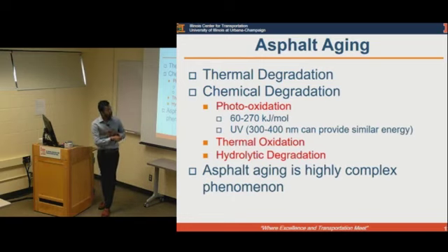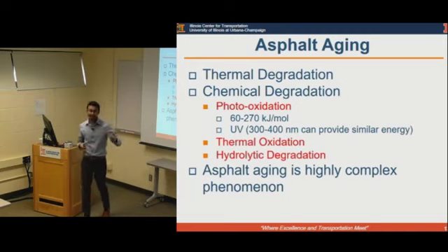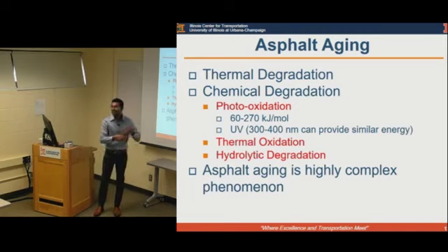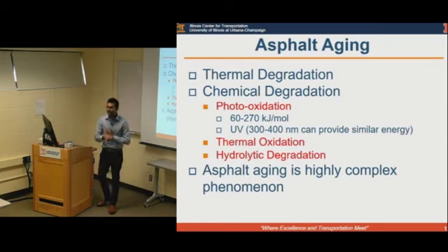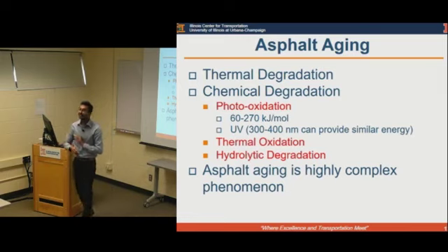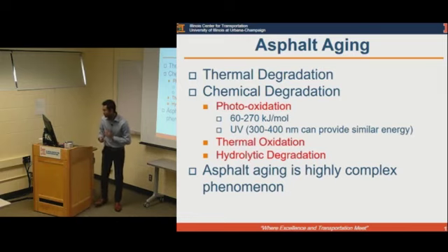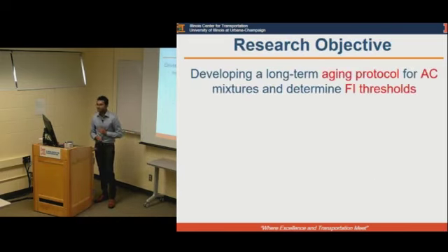Hydrolytic degradation refers to moisture damage. Now, the presence of water, again, in the presence of heat or an energy source, can cause the binder to react with water and then further degrade the binder. So all these phenomena are happening at the same time and can result in asphalt aging in general. So it is, as said, a highly complex phenomenon.